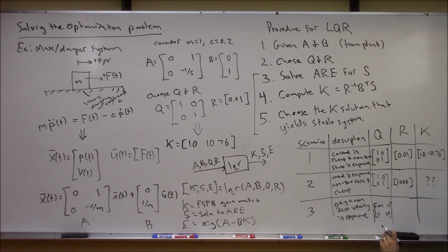So as you can see here, they are clearly mismatched. So the second state will be penalized orders and orders of magnitude more than the first state here. And then finally, the R matrix, I don't know, let's just choose 1 here, because in this scenario, all we want to show is the mismatch between the two states.